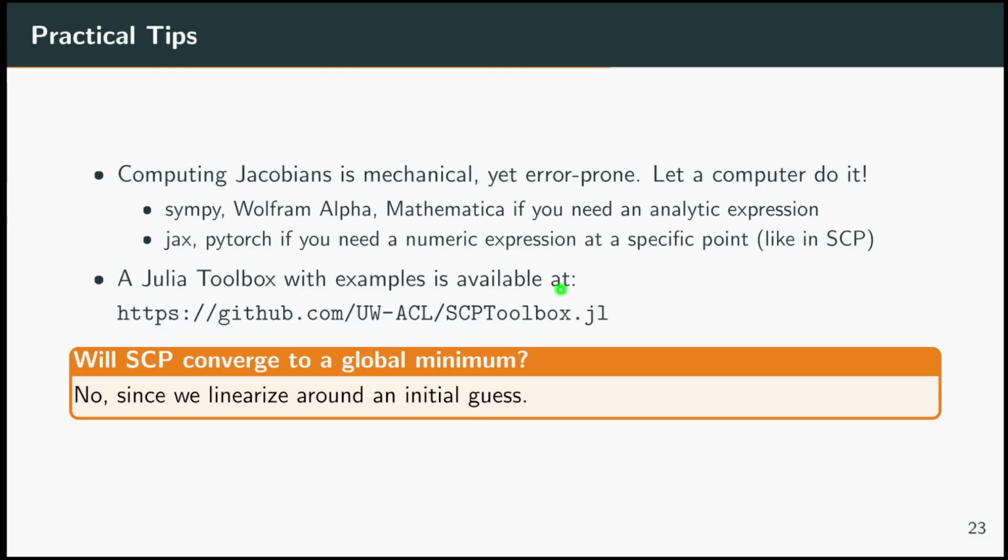There are many papers that claim, oh, it's easy because I can just use a straight line and it just works. But it really depends on your environment setting. If you have a motion planning problem that is almost forest-like, so you just have some obstacles scattered, and you initialize with a straight line, but to avoid the trees you just have to go a little bit left and then a little bit right, then of course you just locally change your initial guess.